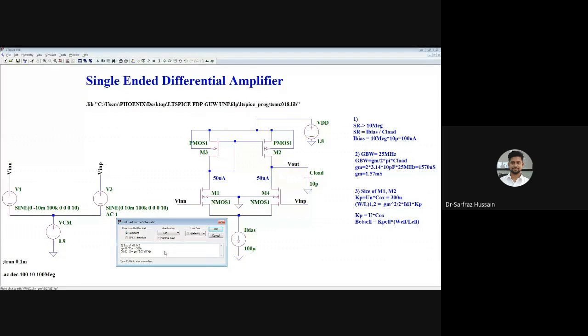So let us write down the value that we are getting. 0.00082, and here we need to check this one also. So gm square, milli into milli, that will become 10 to the minus 3 into 10 to the minus 3, that is 10 to the minus 6, divided by ID is in microampere, so this is 10 to the minus 6, and Kp is equal to 300 micro, so this is also in micro.